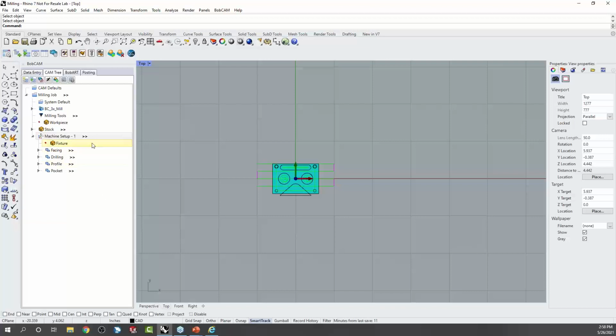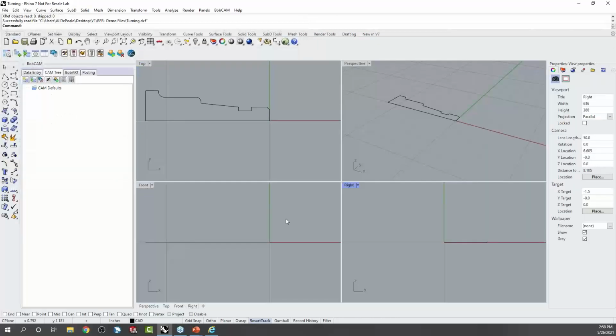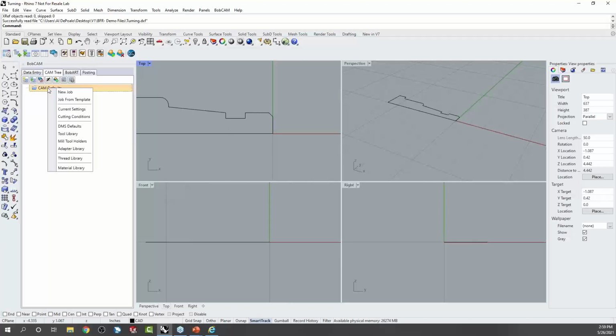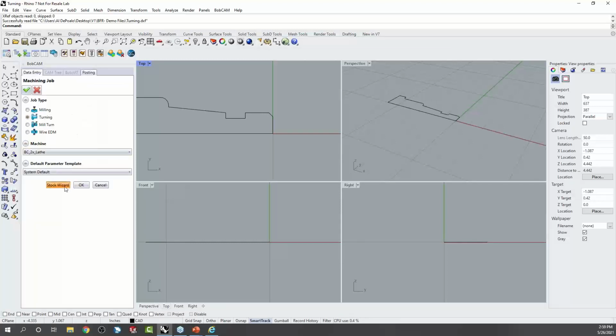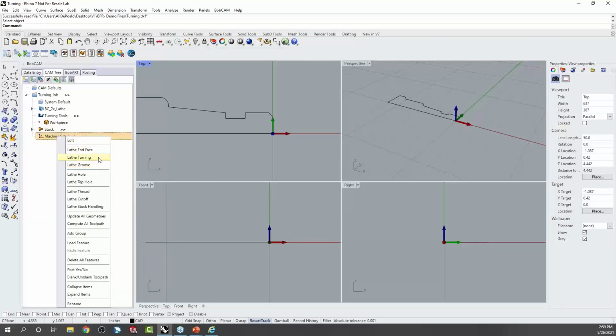Okay, so like threading, if you're on a turning job and you have a groove spiral path, if it's a custom form or something like that, that may be a little more difficult. Generally speaking, if you're going to get into a thread or some kind of spiral, we're going to use a threading cycle. Let's look at this real quick. That's right off the top of my head, that's how I would approach it.